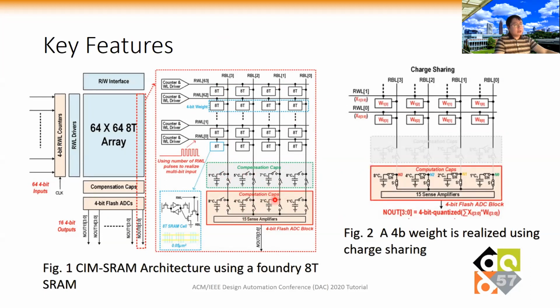And here the idea is to use a capacitor array with different capacitance to do the charge sharing. I think there are 2 steps in the computation. First one is sampling, second one is to do the analog shift add. In the sampling mode, because we have to compensate for the different RC delay, I think they have compensation caps. So you can get similar latency from multiple columns.